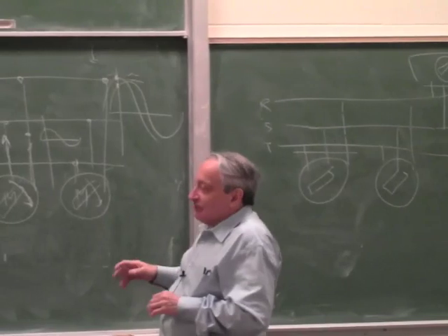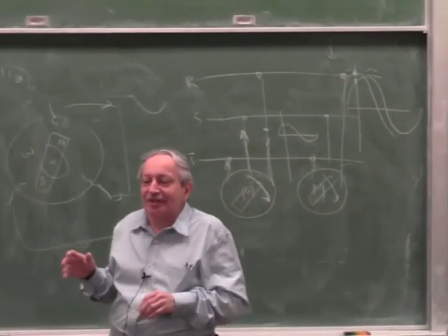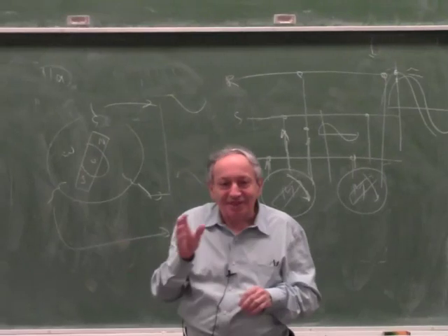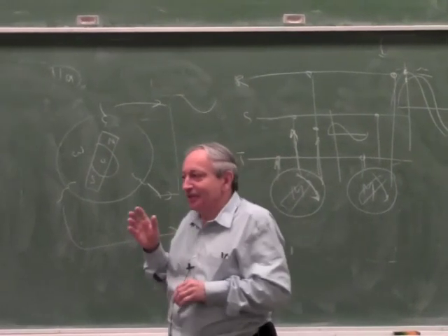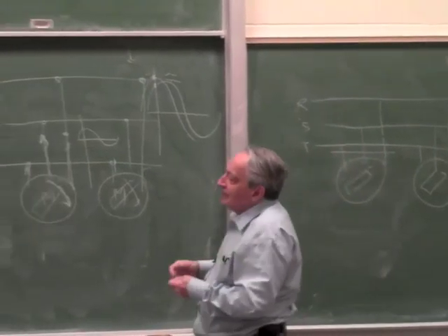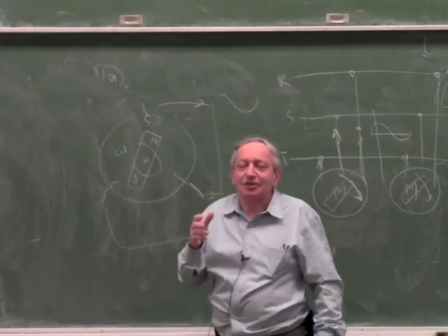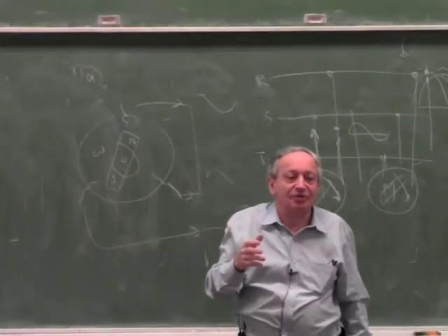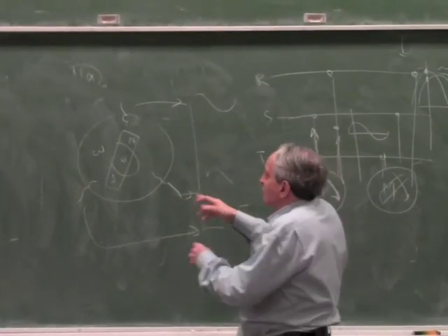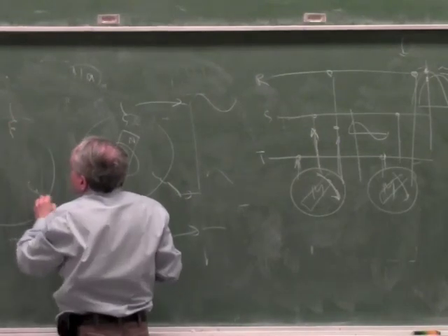Now the last thing I want to raise is how do you do regenerative braking in an induction motor? Because that's actually very tricky. An induction motor is not phased to a grid, but on the other hand, an induction motor doesn't have magnets. Remember, the induction motor works because the armature, which is shorted, is always lagging behind the grid.